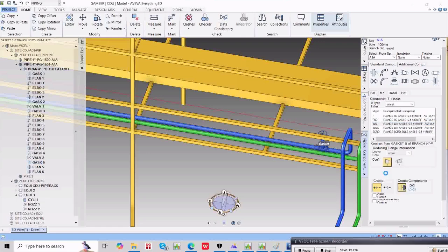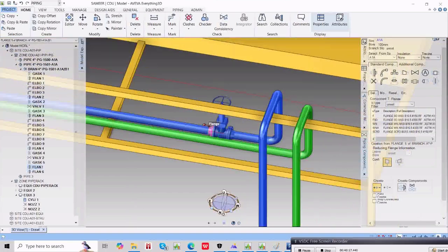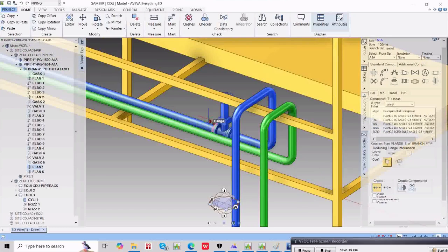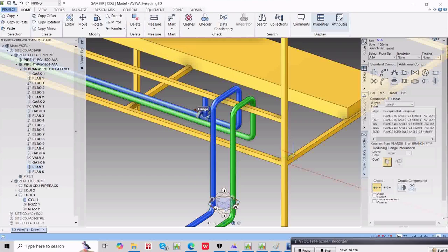Right, okay. So if you have a scenario like this, what you can do is never place this type of valve at the center. You always have to place these kind of valves at the corner. At the corner means here, or the corner-most next to the column, so that the person can put a ladder here, a temporary ladder or stool, and he can access the valve. Because as you know, if you have any component which is flanged, you need to provide access to that.